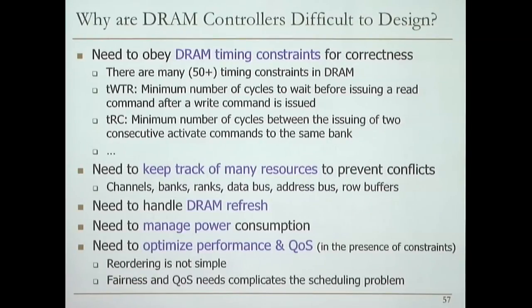There's also effect on, if you want to do perfect reordering, for example, even if you figured out the perfect algorithm to optimize a request, implementing reordering is not simple. That has effects on energy, complexity of the design. And also there's fairness and quality of service, which we will talk about, that complicates the scheduling problem. Because your goal is not just performance, perhaps, but to be fair to different applications. Or some applications have performance guarantees that you need to satisfy, right?